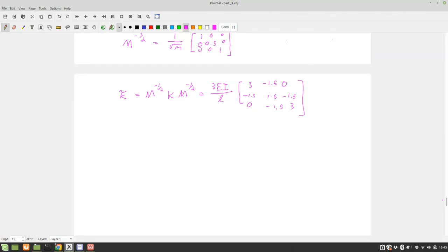So it's A times your vector equals lambda times your vector, right? And so instead of A, what do we use here? K tilde, right? So it's K tilde vector equals lambda vector. And you can solve that by putting the determinant of that equal to 0 and finding your roots, then getting your lambda values and then multiplying your lambda values through to get your vectors. Or you can put it into MATLAB, right? Or Python.